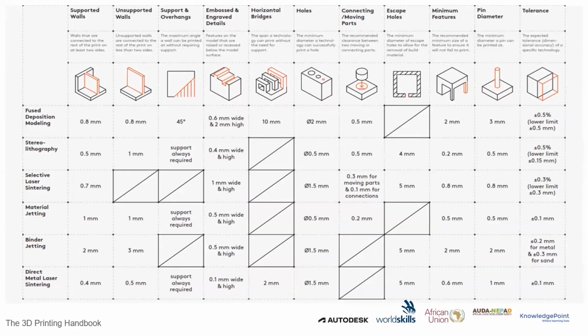a design that we can send to anybody or any 3D printing service, and they can push it in, slice and print without issues and without returning your work because you did designs and didn't consider manufacturing. And this is also very critical and applicable when you're designing for any other manufacturing technique, whether it's injection molding, or sheet metal fabrication, or CNC, and all that. These rules and guides are applicable for each manufacturing technology. And even within some manufacturing technologies, there are peculiar rules that are particular to the different technology. Like in additive, you have different technologies inside additive, and then you also have specific rules depending on the machine itself. So it's very important for us to know this.